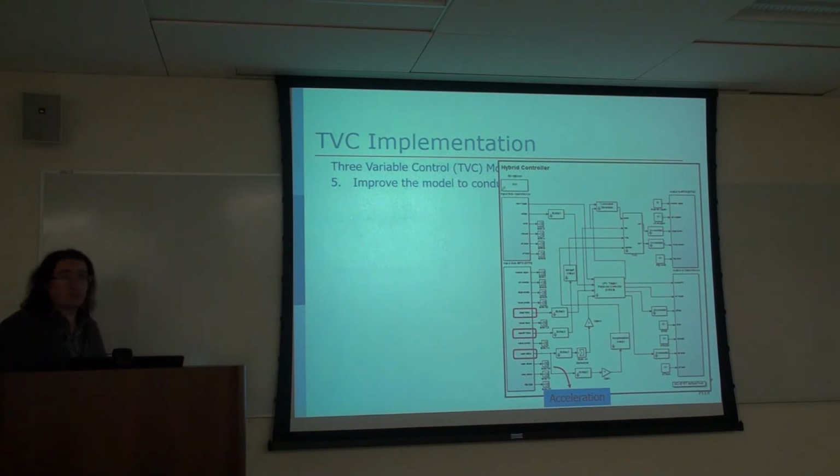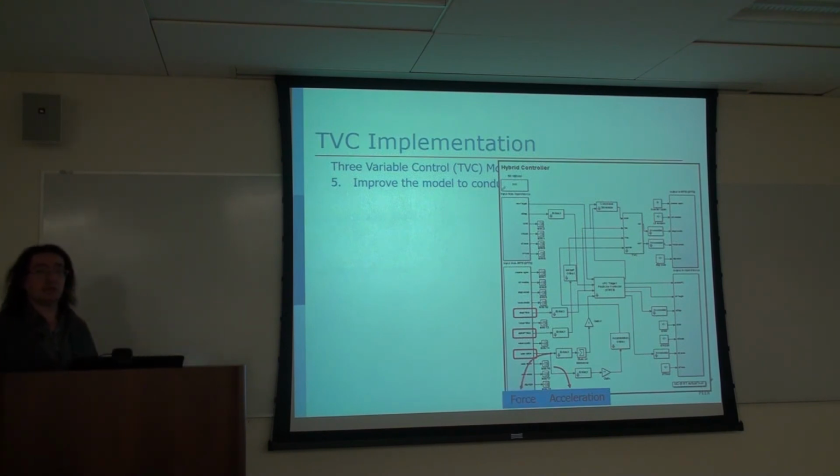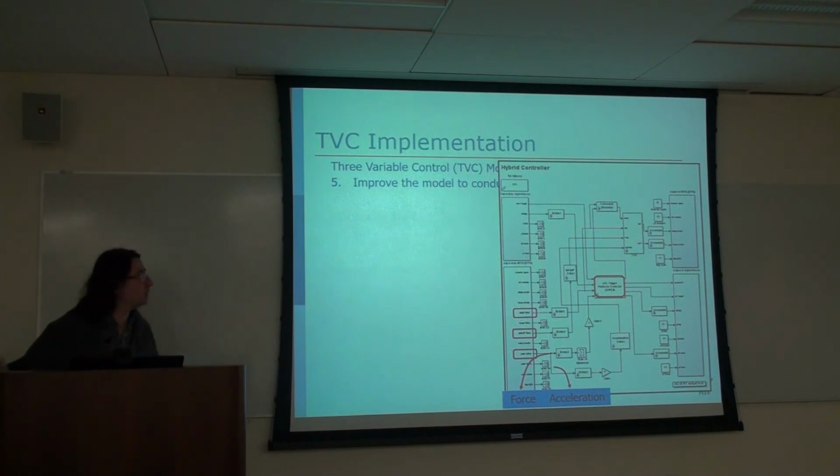So again, similar to the case of the ground motion, we need the displacement feedback, acceleration feedback, and the delta P feedback. But here, in addition, we need the force feedback because we are running the hybrid simulation. So this box is the predictor corrector that does the prediction while waiting and does the correction when we get the next command.